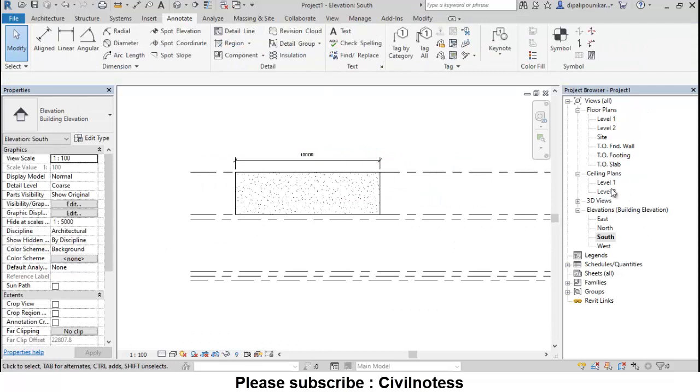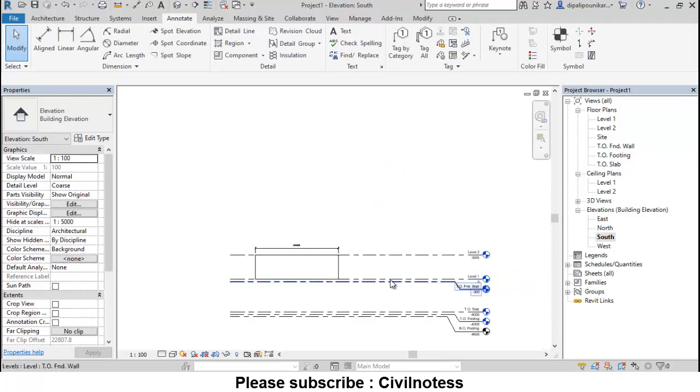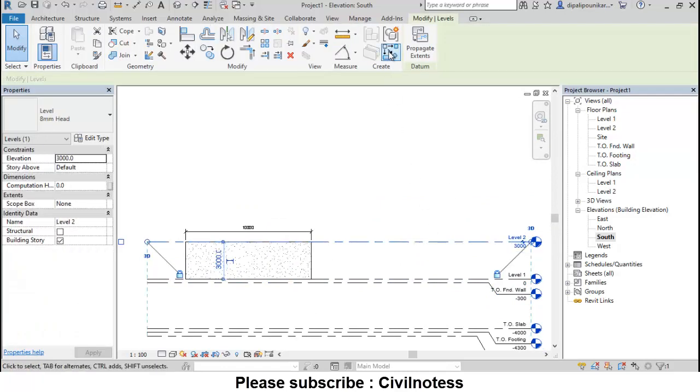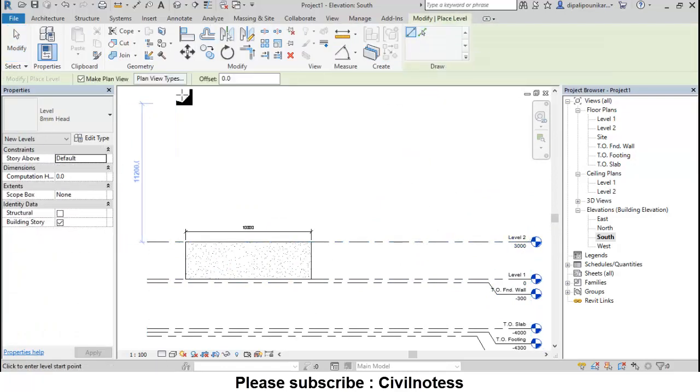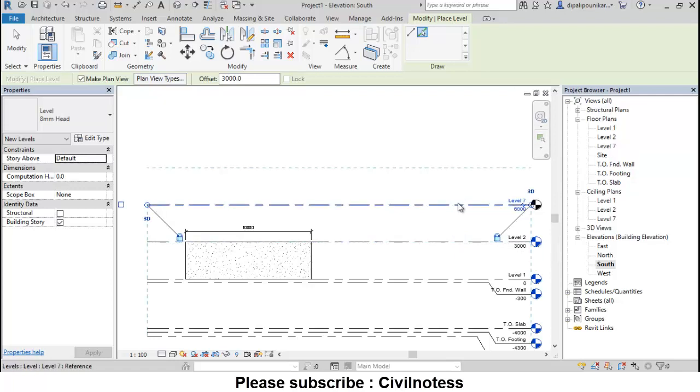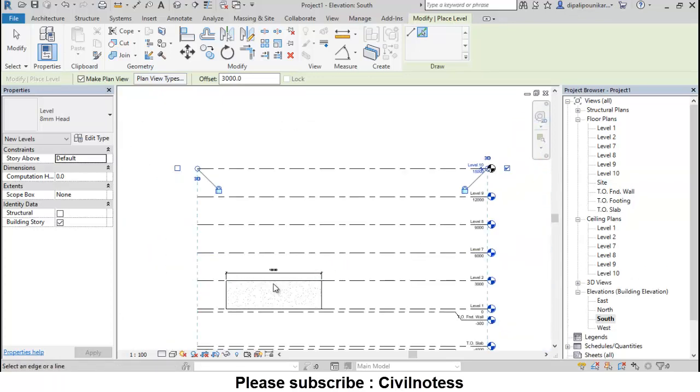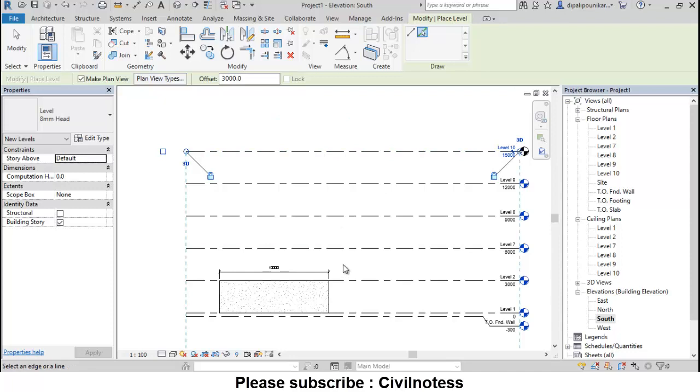This project browser window helps you to create more levels. If you want to create more levels, just select this one, click over here, provide the offset of 3000, and click here, and then just select this particular one, not click, just select. You can see the line reflect over here. Just click, again select, just click, again select, just click. So you can see I have created a G plus 4 story building. Now you can rename the names from here.